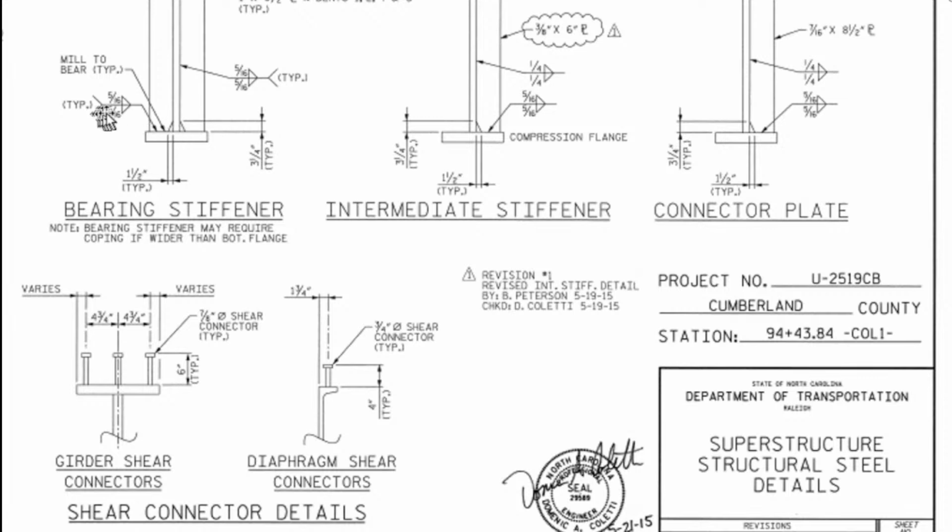So typical. The connection could be a welding or the surface. Note, bearing stiffener may require coping if wider than bottom flange.